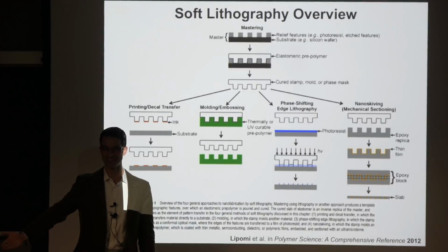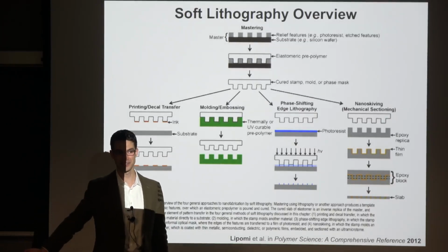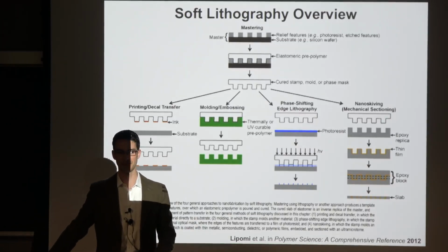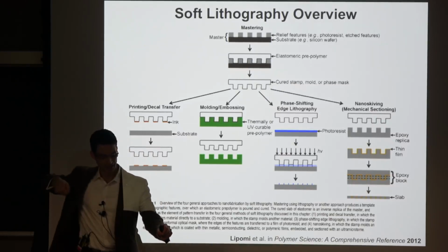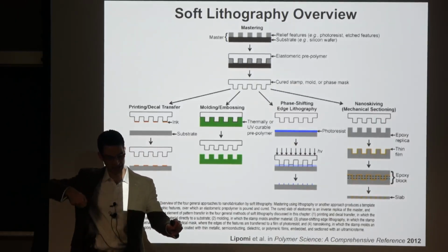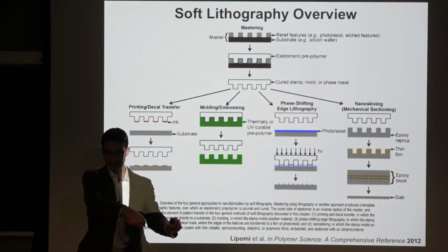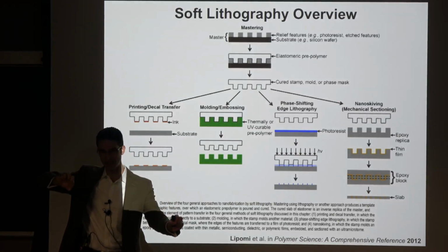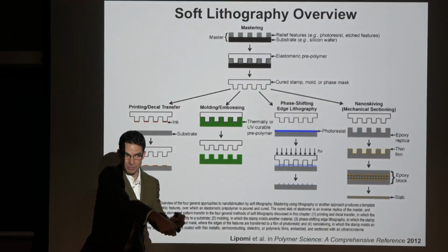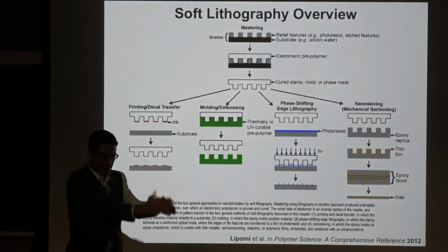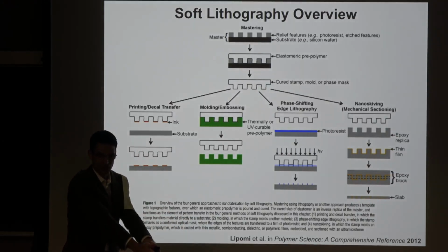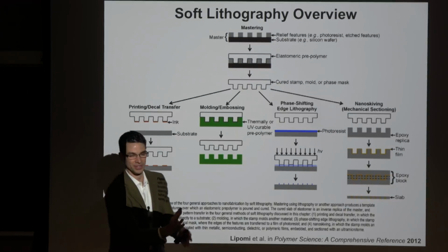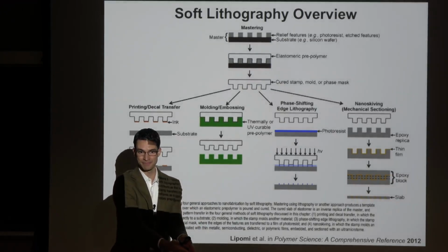It's actually a very interesting geometric argument. You actually increase the effective sharpness of the knife, because as you move a knife with respect to the workpiece, and you draw the path of travel from one end of the knife to the other and project that angle down, you actually have a sharper effective edge, because of the relative motion, than you do of the knife itself.